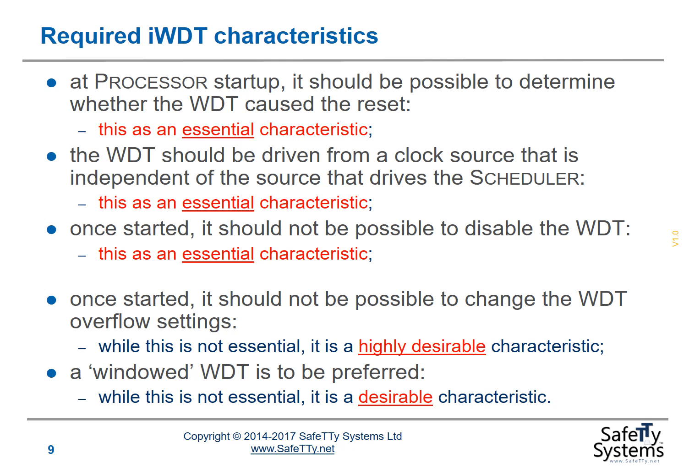Once it has been started, it should not be possible to disable the watchdog timer. Again, this is obvious: if we have coding errors, for example, in our system, and it's possible to disable the watchdog timer, then that will leave our system rather vulnerable. So I see this again as an essential characteristic.